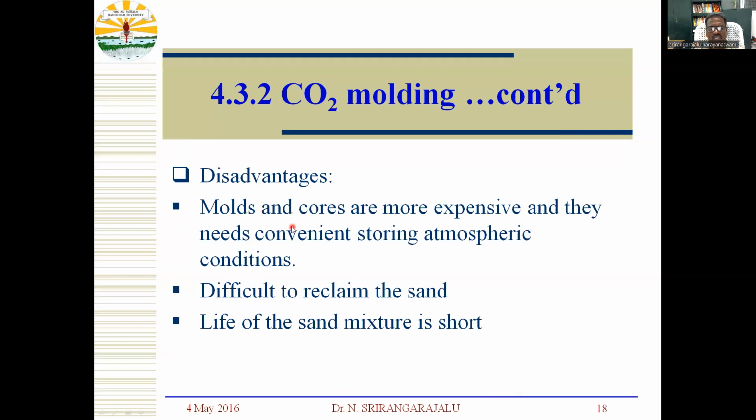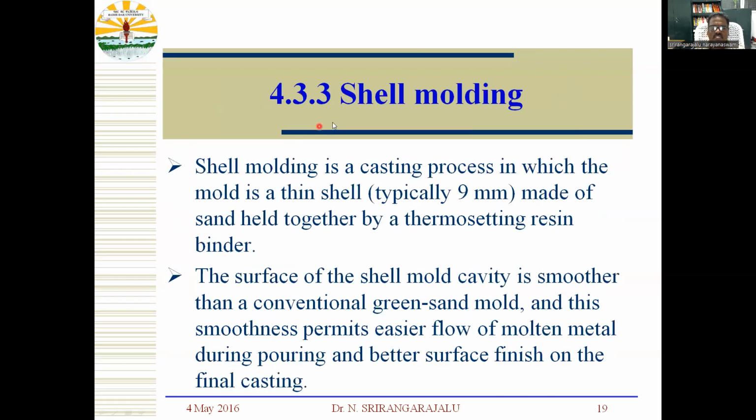Disadvantages: molds and cores are expensive, and they need suitable storage atmospheric conditions. It is difficult to reclaim the sand. The life of the sand mixer is short. So next we will discuss the shell molding process.